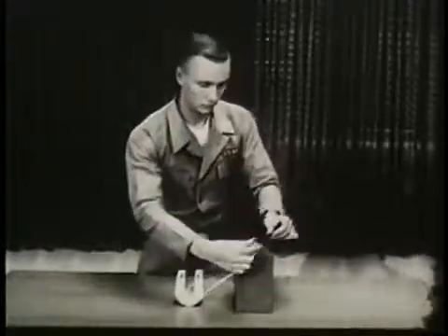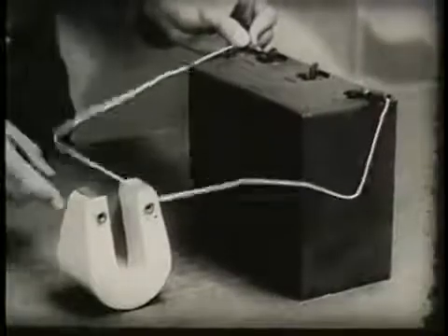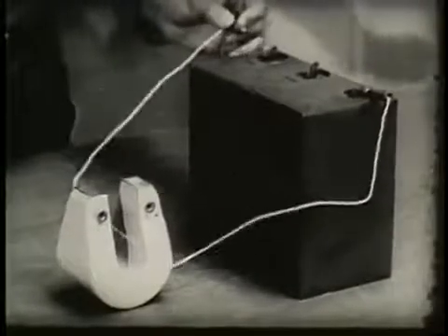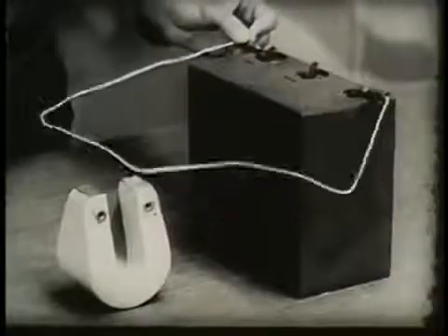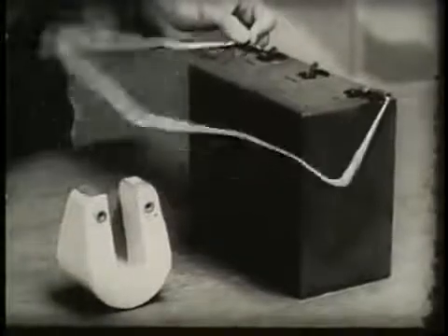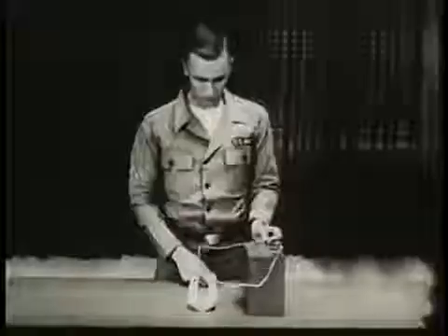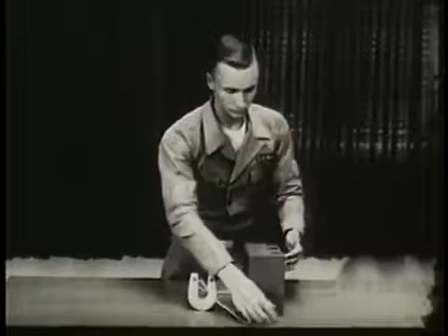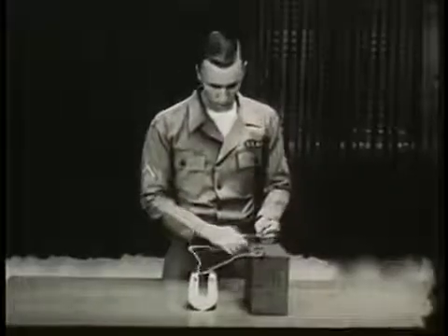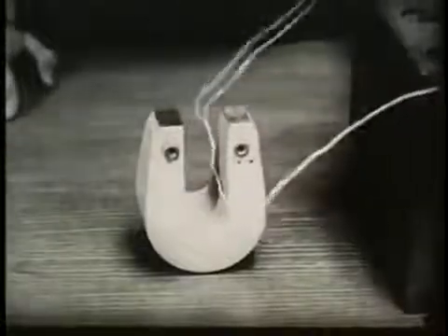Motor action can be illustrated by attaching a power source to a conductor which is inside a magnetic field. The electric current creates polarity in the conductor. The south pole of the magnet attracts the north pole of the conductor and repels the south pole. The north pole of the magnet attracts the south pole of the conductor and repels the north pole. This creates movement, depending on the direction of the steady magnetic field. The movement also depends on the direction of the current flow through the wire. By changing the polarity of the battery, the conductor now moves in the opposite direction.